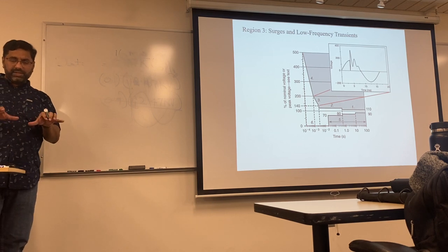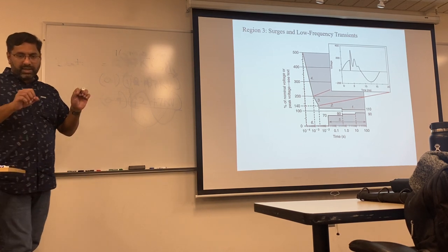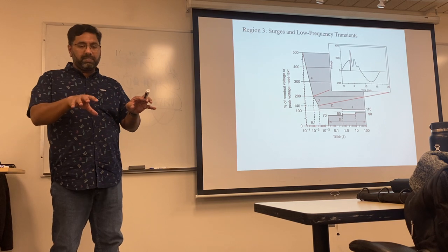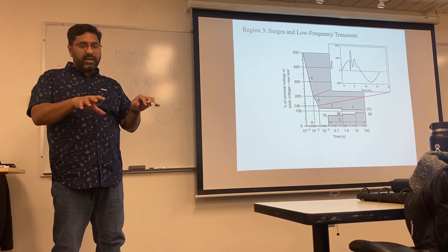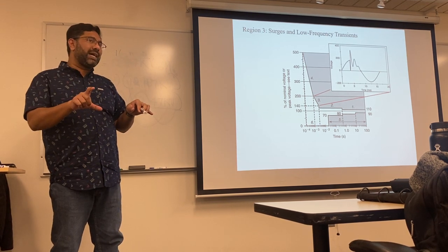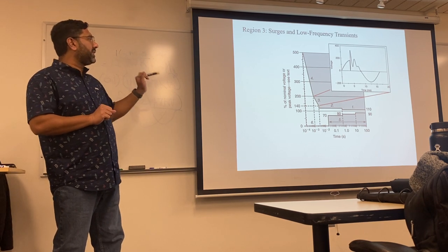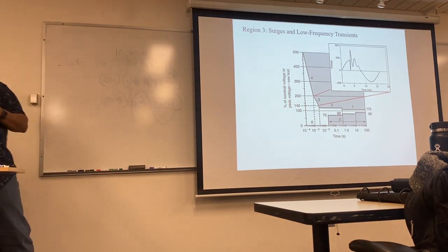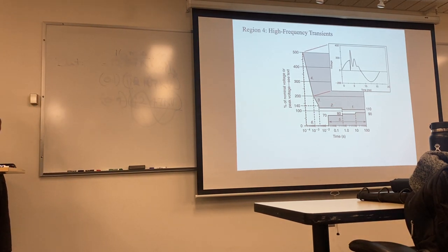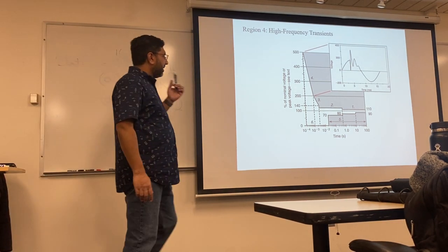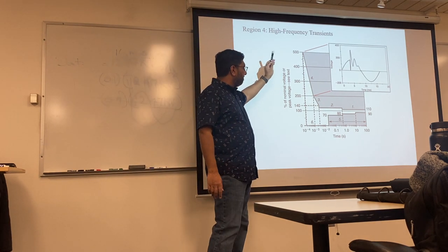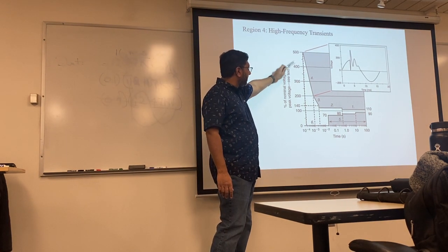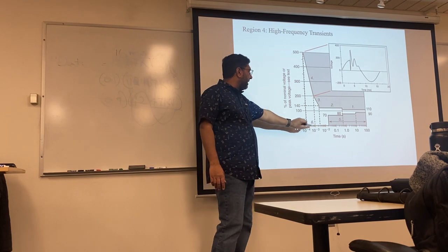You use different kinds of lights, at least it used to be like that. You put a bunch of different lights, and then you measure their spectral activity and you figure out, oh, it's not just 60 hertz. There are other hertz that are being seen. Similarly, the high frequency transient is on, you can have high frequency, but like I said again, when you have a high frequency, pretty sure you're going to see very high voltages, but that's a very tiny, weeny period of time.